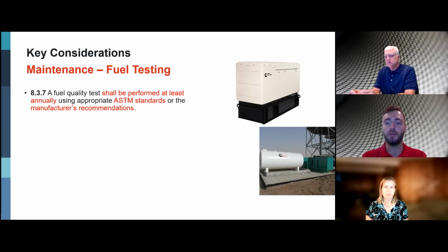Another key tip is getting a proper baseline test with a diesel fuel sample as a result of the fuel as it is delivered in the tank during the commissioning phase of the generator set, which will be most helpful for the facility owner down the line.